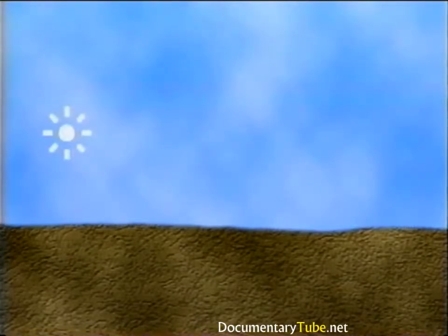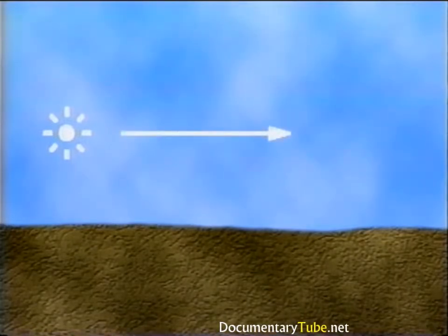We can start by talking about a simple propagation path, the path going directly from the source to a receiver. Besides geometrical spreading, which causes the sound level to decrease as it propagates toward the receiver, the propagation medium itself can possess inherent losses. Atmospheric absorption is the attenuation of sound during its passage through air. For propagation distances related to highway measurements, this attenuation is only significant at very high frequencies, greater than 5,000 Hertz. It is, in general, small compared to attenuation caused by other propagation mechanisms and can usually be neglected.